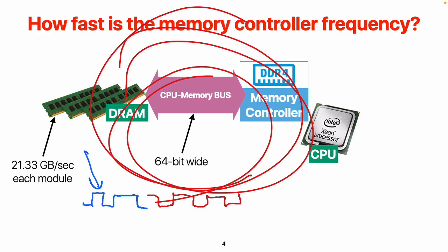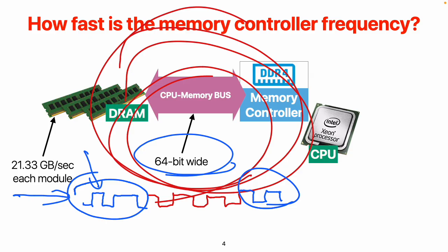And after you send your data, again, your signaling would have some kind of postfix to tell that the transaction is done, right? And because this is only one way, at this moment, only one direction can do this, right? Now, if you do it every 8 bytes, what that means is that for every 64 bits, you need to pay the overhead of this prefix and postfix.